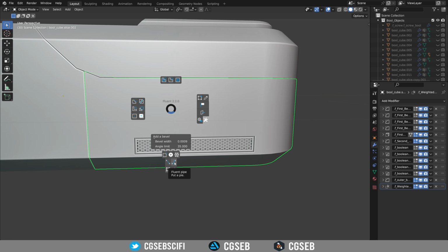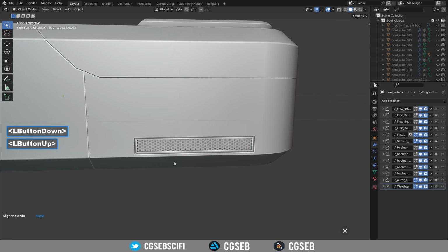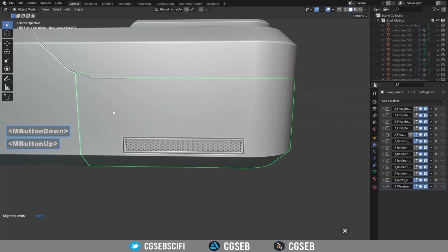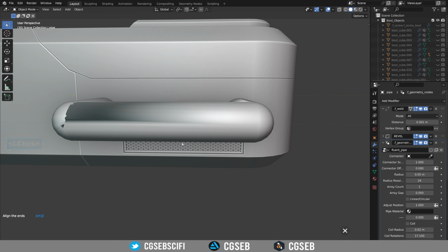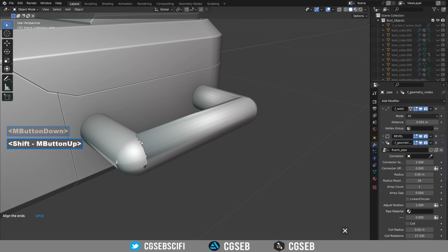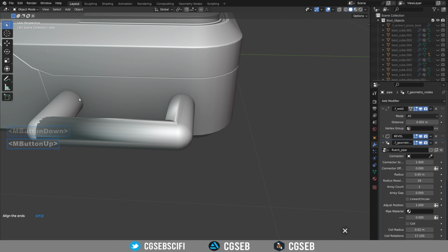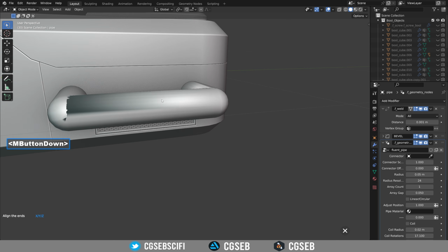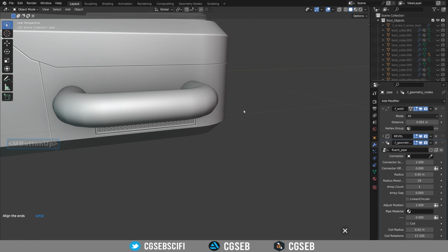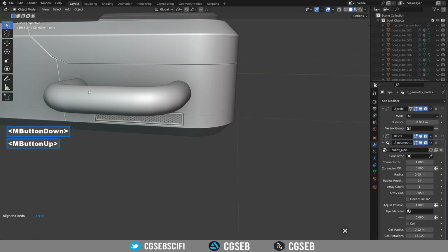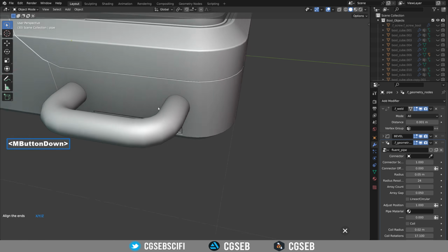And if you select object, then go to pipe tool, you click, you will see a first dot. This is where the pipe will start. And if you click again, it will draw the pipe. Right now, it's a little bit buggy because you need to say, okay, I would like to align those 2 points on Z axis. So if you press Z, those 2 points will be at the same height.